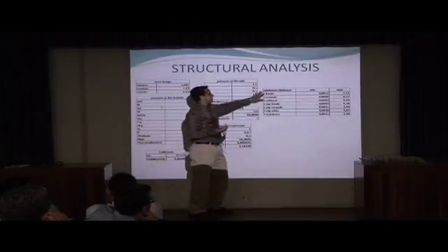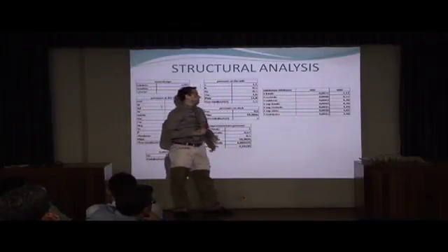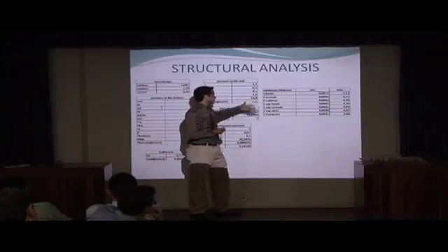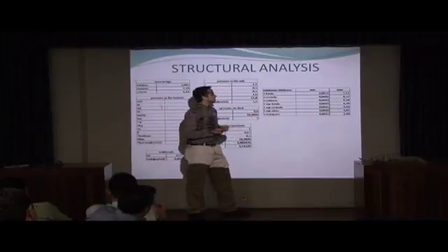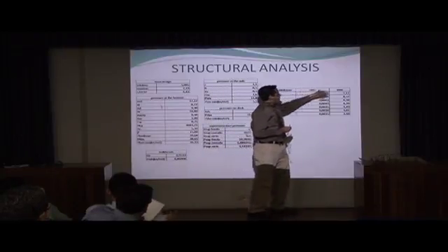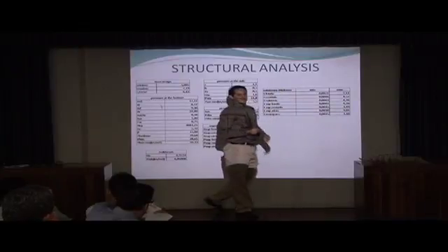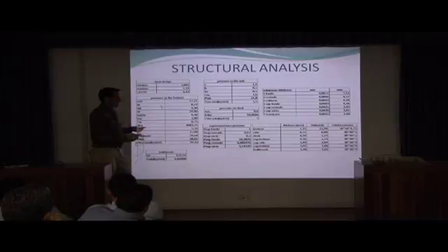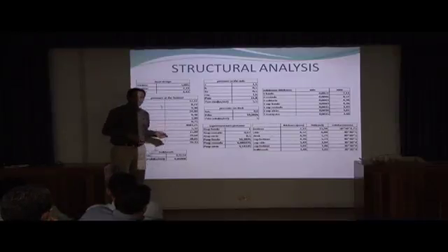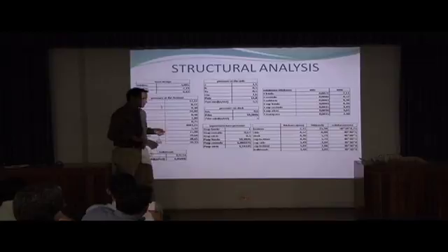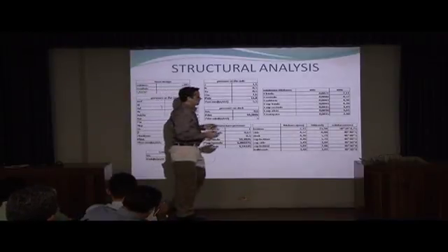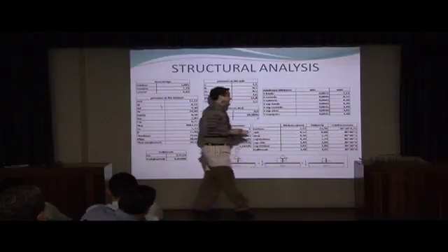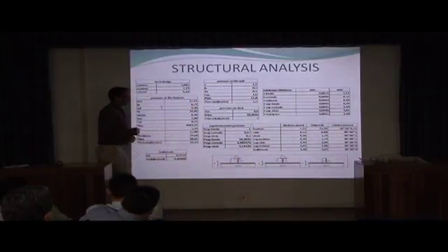the thickness, the minimum thickness that I put in the ship. For the bottom, for the side, for the deck, for the superstructures, and for the bulkheads, here I have it in meters and millimeters. This is the thickness for the plates. Then, the article tells me that with the thickness I calculate the minimal section modulus, and then in a table, I have the reinforcement. The reinforcement is in T.